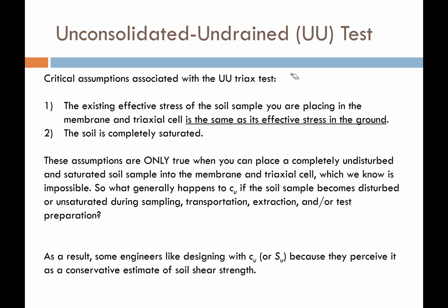First, we're going to assume that the existing effective stress in the soil the moment we close the drains is the same effective stress that the soil was experiencing in the ground. So in other words, from the moment we pulled it out of the ground to the moment we closed the drains in the triaxial device, the effective stress that the soil was feeling did not change. That's an assumption that we make.